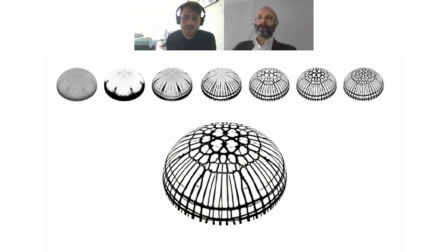So to explain a little bit about what topology optimization is, it's an iterative process, as you can see on the top there. So we start off with a mesh. Each mesh element has a different density, and then we analyze it to a given load case, and the elements which have high stresses and strains, they're obviously very important to the structure. So we add more density. The ones with low stresses and strains, we take away density. And then that's changed the structural behavior. So we analyze again and we iterate and we iterate. And you can see snapshots of this process here until we converge on something.